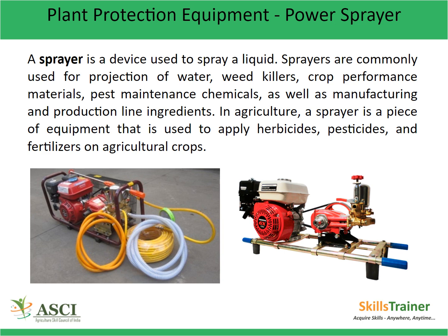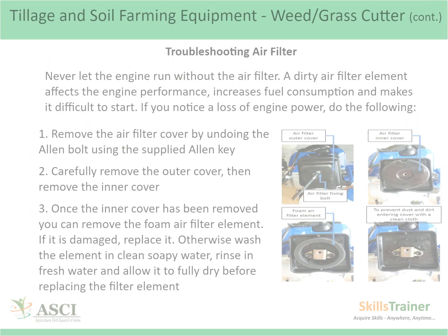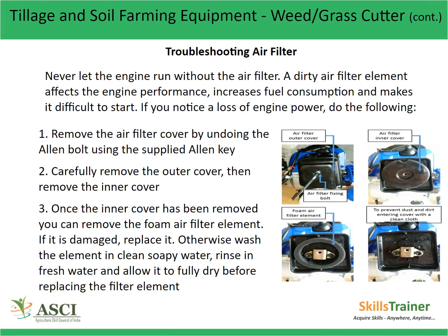Do the following. Remove the air filter cover by undoing the Allen bolt using the supplied Allen key. Carefully remove the outer cover, then remove the inner cover. Once the inner cover has been removed, you can remove the foam air filter element. If it is damaged, replace it. Otherwise, wash the element in clean soapy water, rinse in fresh water, and allow it to fully dry before replacing the filter element.